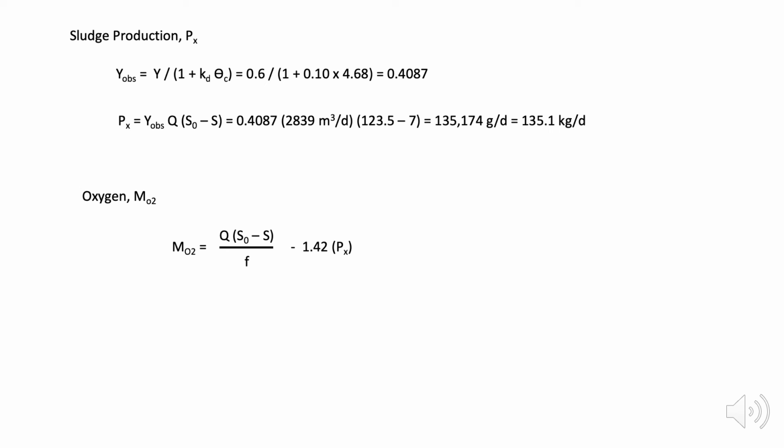This is, remember, the expensive part of the system. And I have to supply as much oxygen to the system as is being used up by the microorganisms that are using the BOD in the system. So the amount of oxygen that I have to put in there is kind of equal to the amount of BOD that's exerted in the system. But remember, we said there's an interesting thing that happens here.